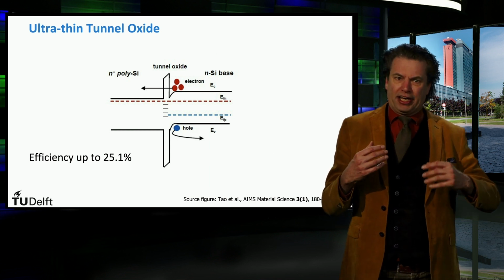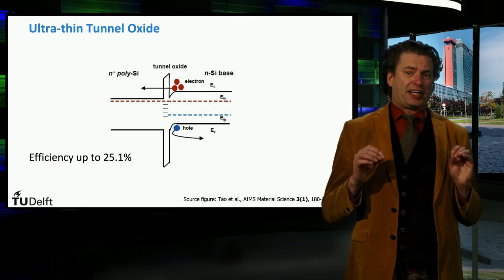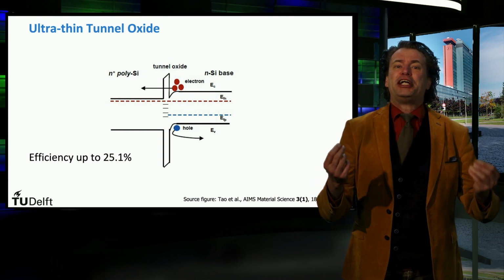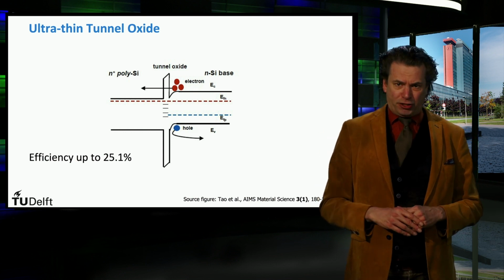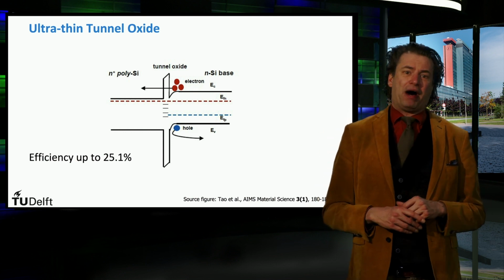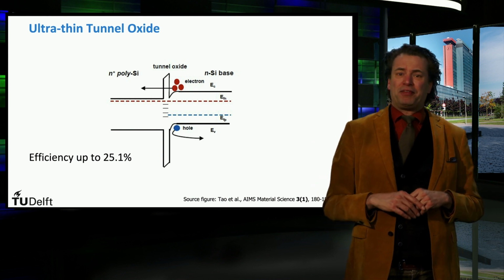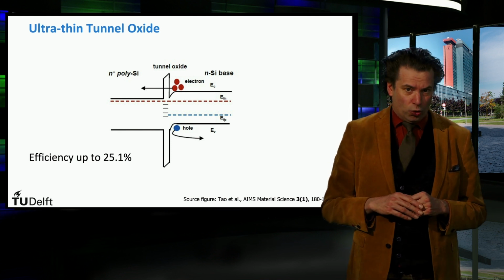Now, since the oxide layer is present, it is almost impossible for the minority carriers, which are holes for the n-type wafer, to reach the back contact of the cell, as they cannot pass the potential barrier introduced by the oxide layer. In addition, you see in this example that the electrons experience a smaller barrier than the holes.